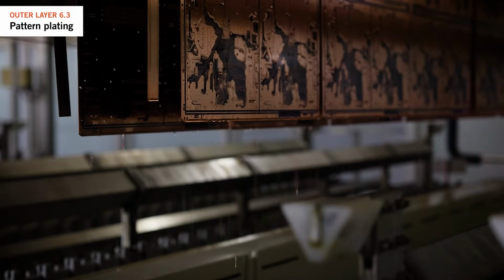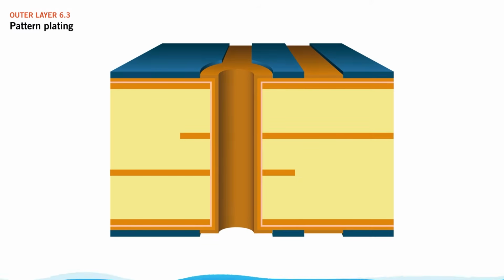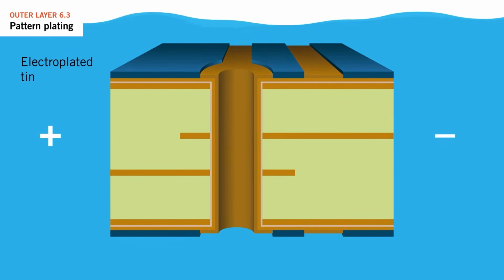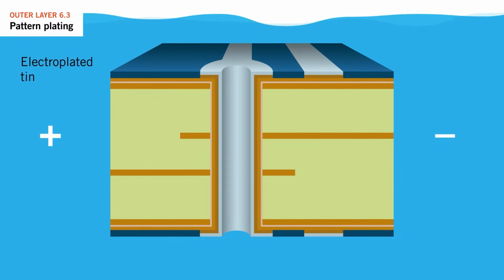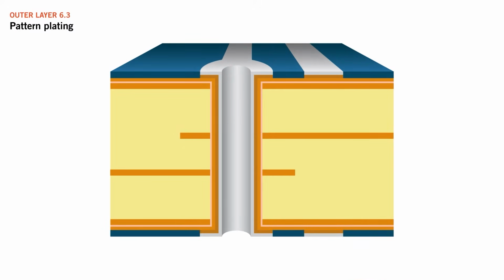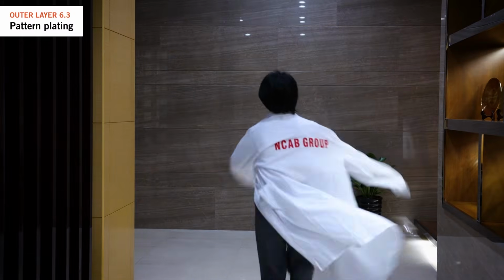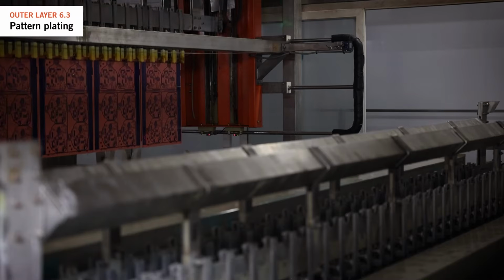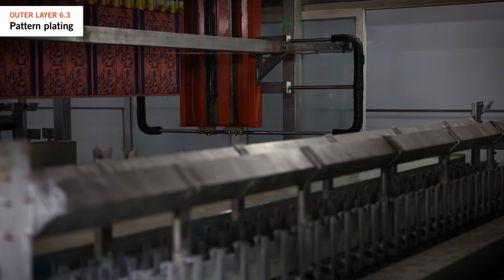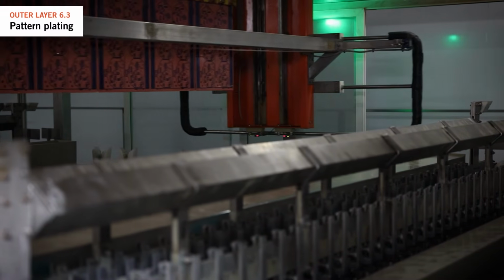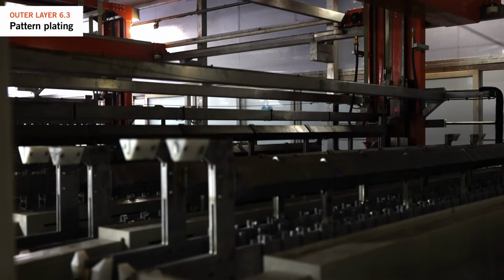Once the additional copper has been plated, then a deposit of tin is applied on top of the plated copper in the same pattern to protect the plated copper underneath during the subsequent processes. We check and audit the control of all plating parameters, including the process control for all of the chemistry and the setup of plating currents, which determine deposit rates.